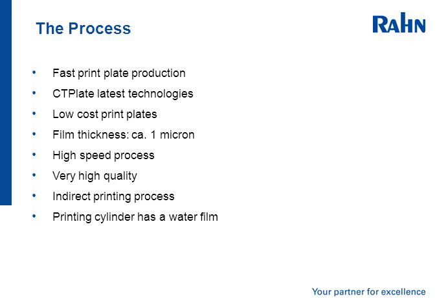It is an indirect printing process. The plate is offset onto a blanket, so it is a planar, flat printing surface. And the print cylinder has a water film or fount solution which allows the non-image area to stay clean.